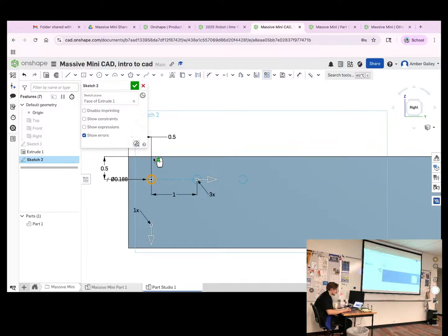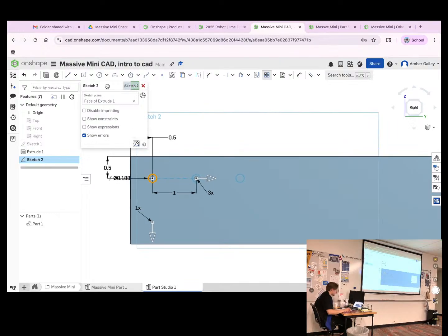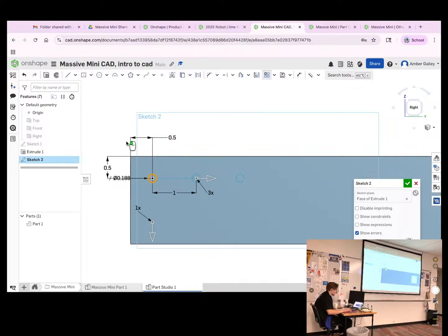At this point, number one, I'm going to flip my top line down, because I don't want the circles to be going up. I want them to be going down on this one. I'm going to click this one time to make it 3. And then it's way too far apart. So instead, I'm going to make it 1/2 inch.